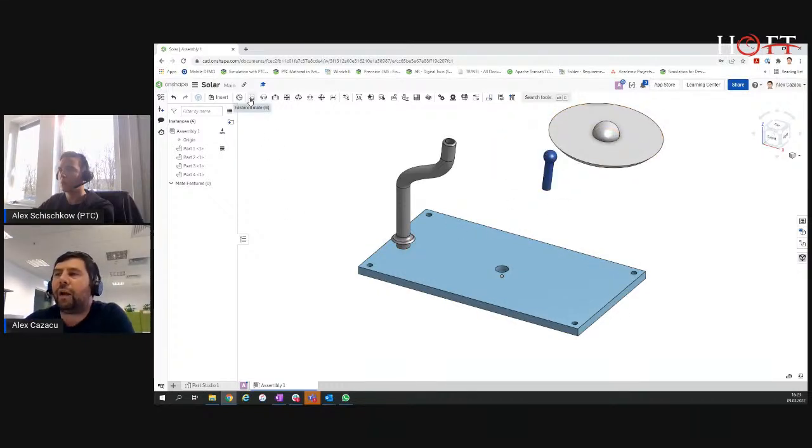In Onshape, we have a fasten mate, revolute mate. This allows just revolution. Of course, this is like bounded. Revolute mate allows revolution. So I will be using one between this and this. And of course, this one and this one. We have also the slider mate that allows only translation.